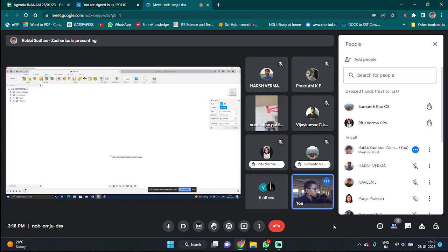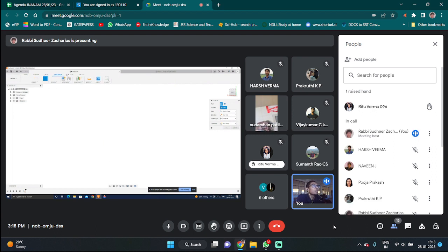In such cases we can't directly import or export our 3D model into the simulator tool. It will form a mesh around the 3D object, and then a single copy in .stl format will be exported to the simulators. Sheet metal we won't be using much. This is for plastics and other utilities, but basically we'll be working with these three options: solid, surface, and mesh.